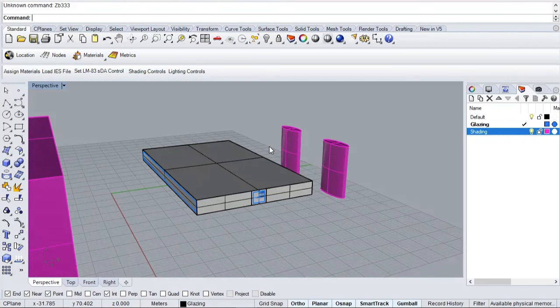or other buildings, vegetation that are used by ARCHSIM to understand where there are intersections between the building form and the sun. So the main point is these surfaces, whether you have them as bodies or not, are used by ARCHSIM to understand where there are obstructions between the position of the sun and the built environment. And that obviously can reflect shading as much as it's obstructions, and the whole point is to give you a more accurate understanding of the effect of external obstructions on solar energy interactions with the building.